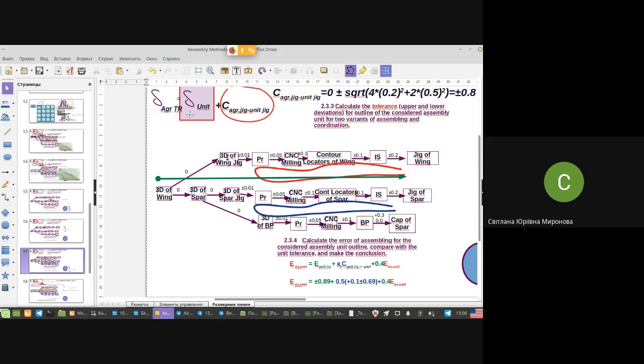But the program generated in G-code, so-called, for a CNC machine in general, next must be recalculated by the machine's inner computer, which is called post-processing, into another program which is suitable for this particular machine. And at this stage, you also might have some losing of accuracy. Look, I wrote here some value.